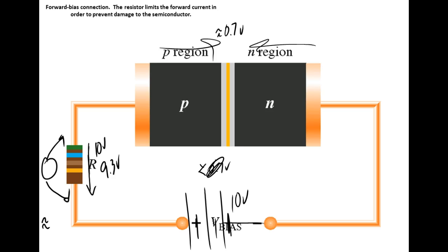But now instead of me coming over here and turning this thing on, we can turn it on with a voltage. And I can turn it off by simply doing what? Switching the polarity of the battery. Now I'm switching the polarity of the battery. You say, what good is that? But remember AC. The positive alternation has a DC average. The negative alternation has a DC average. That means one of the alternations on an AC signal is going to forward bias this thing. And then the other alternation is going to do what? It's going to reverse bias.